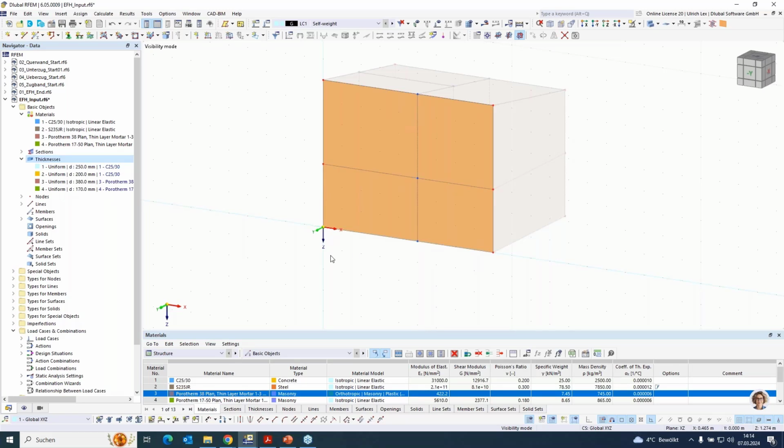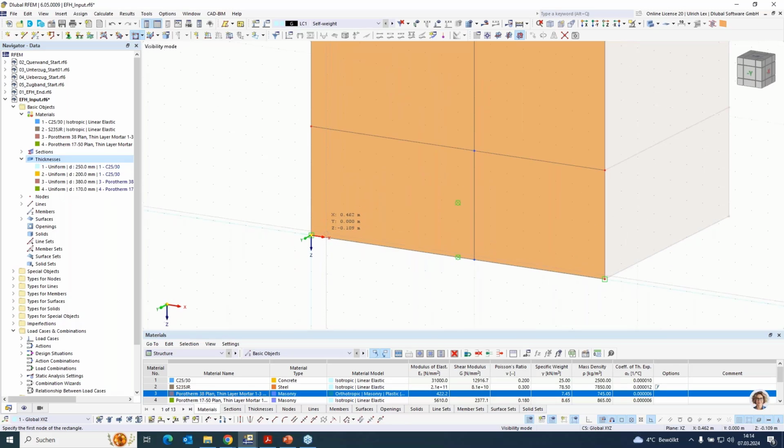I change the space of the grid points, divide the space 2 times, and now I can use the option create a new opening with 250 high and 150 width. I create a new window.